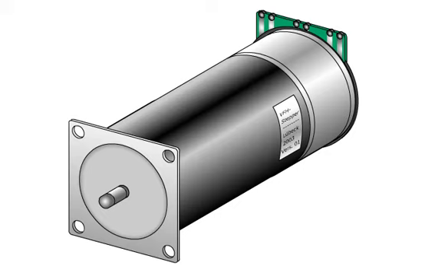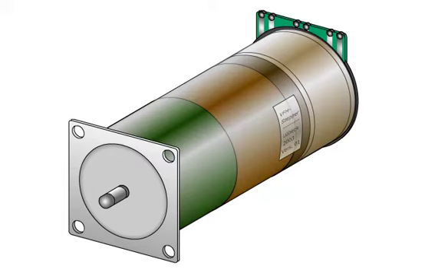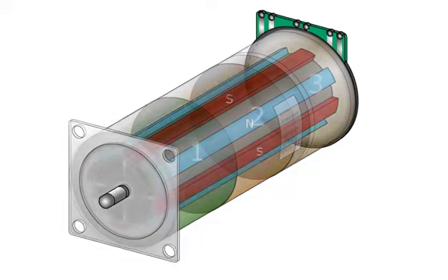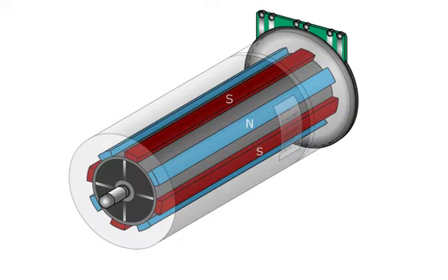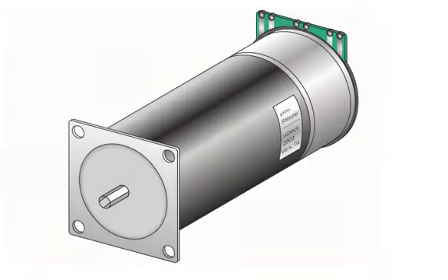A stepper motor generates defined angular rotations. For this purpose, the stator, hence the fixed part of the motor, consists of several electrically and thus also magnetically isolated stator parts. In our example, we have 3 such parts. The rotor, hence the rotating part of the motor, with the motor shaft, consists of permanent magnets that take effect across the entire length of the motor.